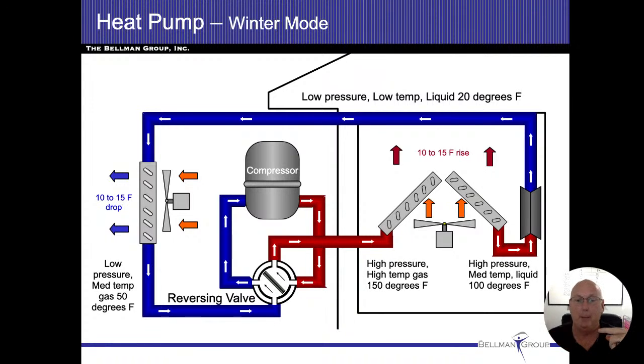As that's happening, I put my hand on it and I feel it. Well, my body temperature is 98.6 degrees. So if I'm 98 and that airflow is 80, that's actually going to feel cool to the touch as the air that's coming over me. So I'm going to feel like I got cold air that's blowing out of the ductwork, when in fact it's actually heating my house, all right? So it's a little bit awkward when you see these things run.